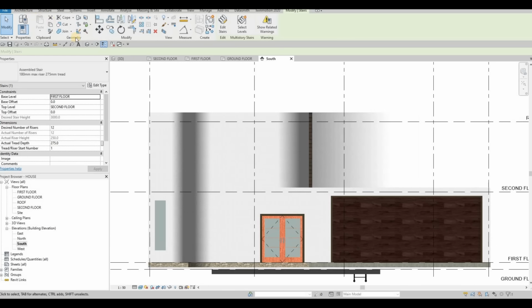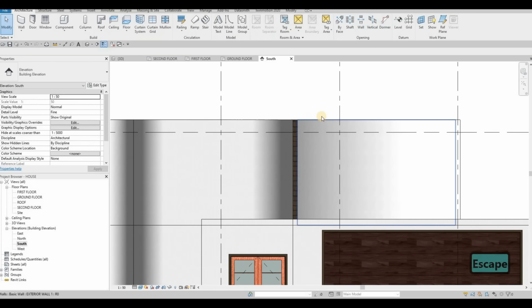So right here, what we're gonna do is SL, we're gonna split from the top. So we're gonna make a split from the top right here, and then from the bottom, and then the middle will be the glass. But instead of curtain wall, we're gonna use storefront, because it's not possible on that sense.